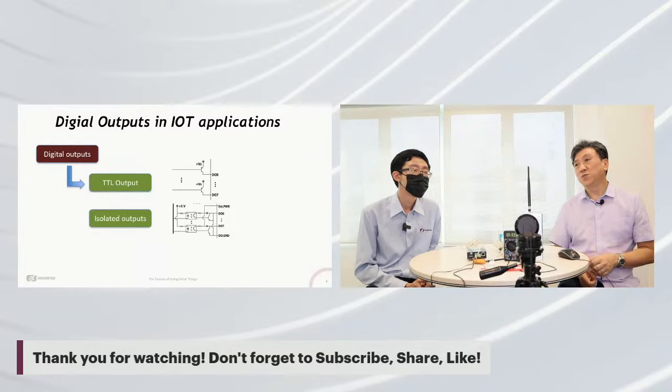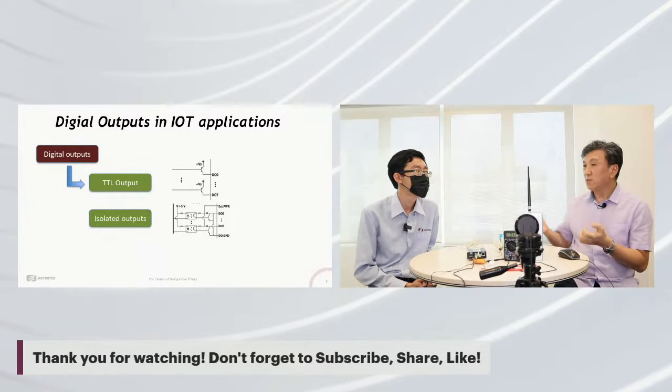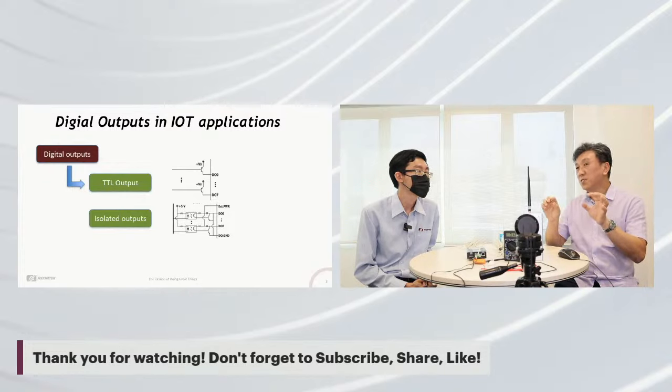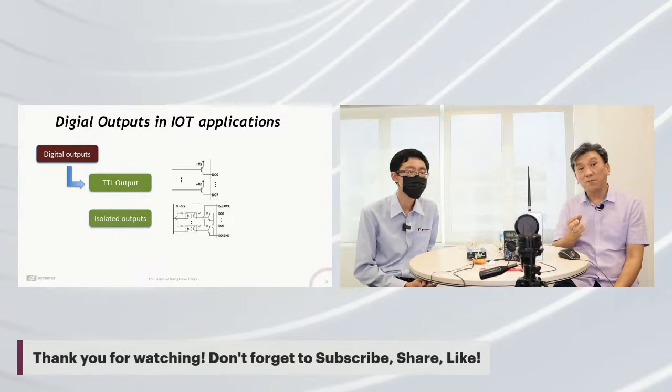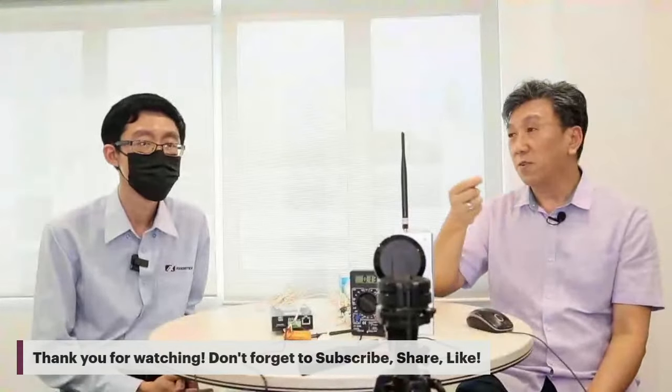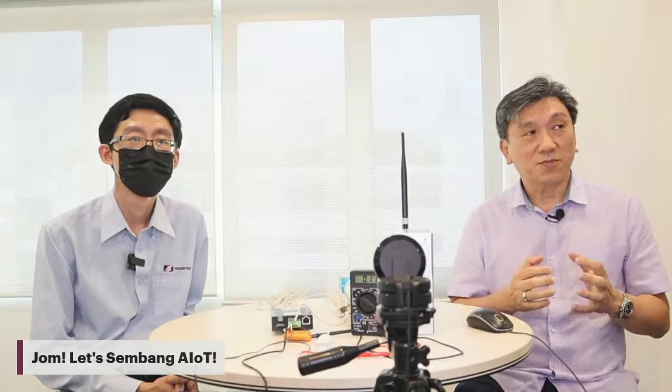So if you have this knowledge, do you think it will be helpful when you want to tap on some signal or sensor from the field? Yes, I think so, because some equipment or sensors give you a voltage output, which we call a wet contact, and some give you a dry contact, which is in relay form. That allows you to know more about how to do that. Let's move on.